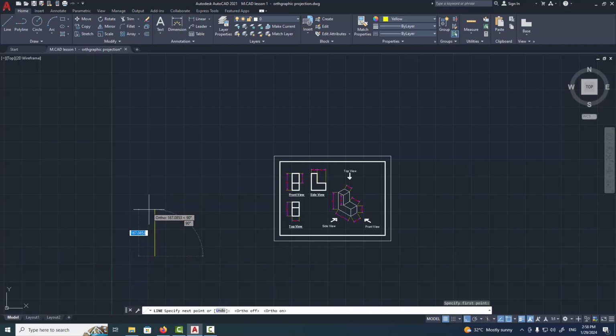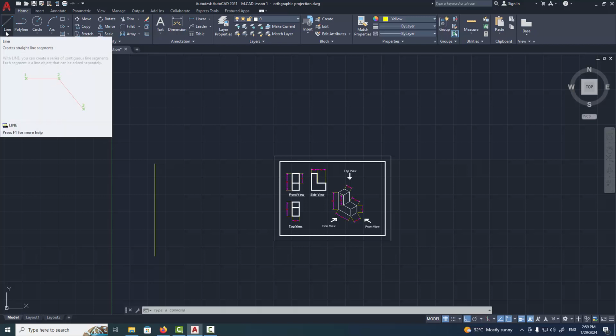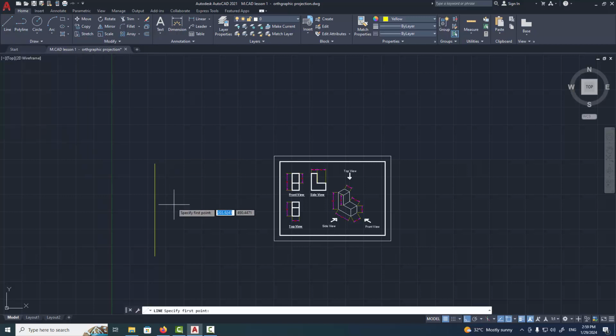It doesn't matter where you extend your lines, as construction lines are deleted once used. Once you specify your second point, press enter and it will exit the line command tool. So to activate the line tool again, I will select it from the ribbon area, then repeat the second line and enter to exit the command. I will select, then draw the third line, then exit the command by pressing enter. This is how we use the line tool.